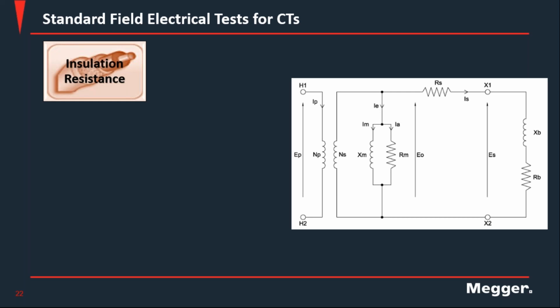All right. Daniel, can the insulation test cause remnants? Thanks, Mike. And there's certainly a possibility. Remember, as a non-written rule, anytime you are using any DC-based method for any measurement, there is a possibility that you can have some remnants in the core of the CT.